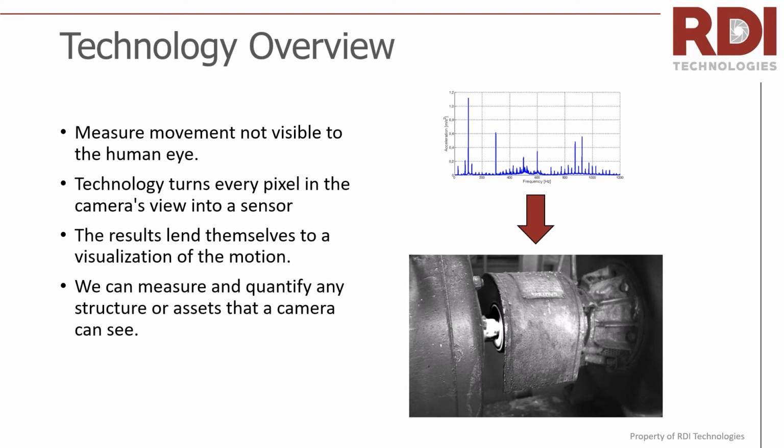We're not going to focus on the motion amplification piece so much, but a lot of the flavor and themes and commonality between cameras and technologies is that this technology allows visualization. It allows us to understand things a little better, because we're not at the mercy of a single point of data collection. So you can see misalignment instead of having to say, okay, the ratio of these two peaks is this amount, so therefore I think maybe it's this fault.